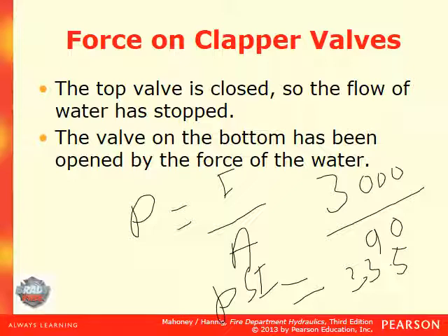And the reason being is because that valve on that side has a smaller square inch area. So we increase the pressure, which will increase the force and open it up and allow the water to flow.